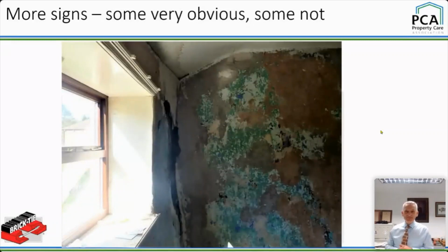We have this one, sometimes it's obvious, massive crack. You could get your fist in the crack between the internal masonry load-bearing wall, by the way, and the left-hand side external wall. That's why I've included this window so you know where it is. You could get your fist in there, all right? Now, nobody's going to miss that. We can see that the external wall's bulging out. It hasn't got any lateral restraint from that wall. There's a sloping ceiling. There might be a bit of roof spread there. We're not going to cover that today, but that might be why. There's all sorts of things happening.